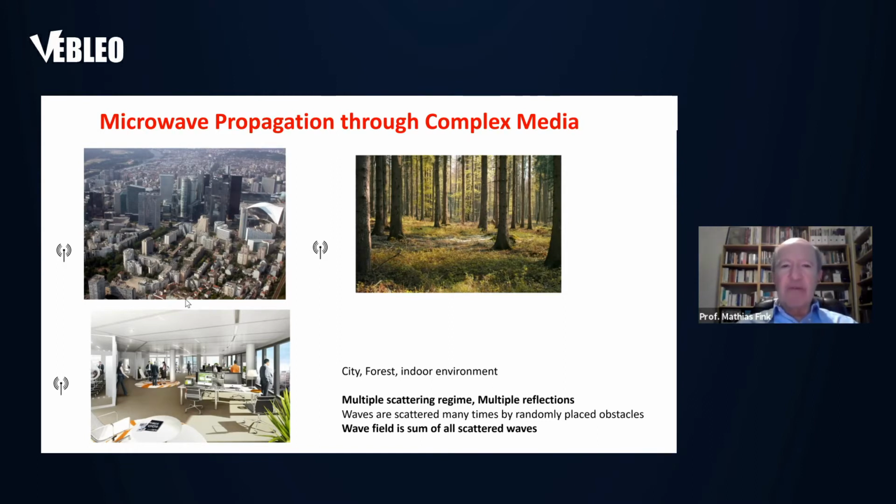First, I want to remind you that when you send radio waves or microwaves in a city or in a room or in a forest, it's not free space. Waves will interact with each building or each object, and the wave will be scattered. And the wave field that you will observe depends on what we call the multiple scattering regime. There is a lot of scattering between each element in the city, and there are multiple reflections. In fact, the wave field is the sum of all these scattered waves.